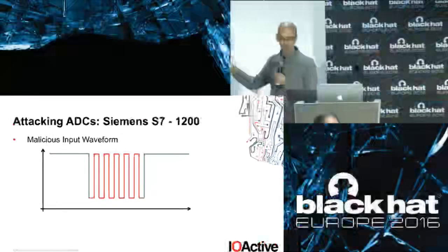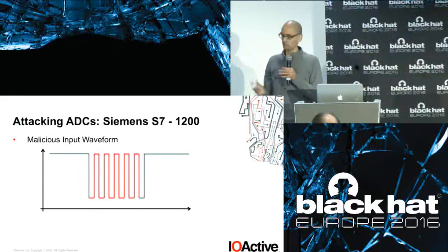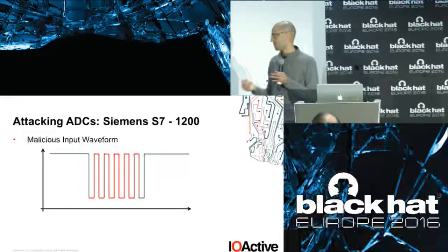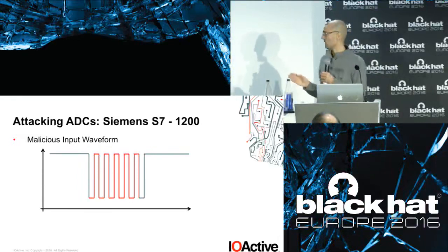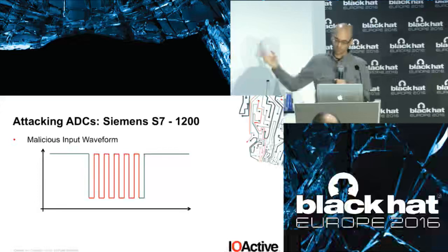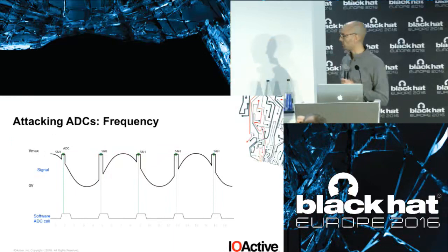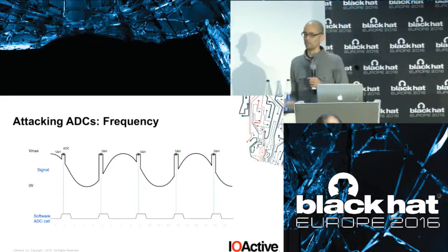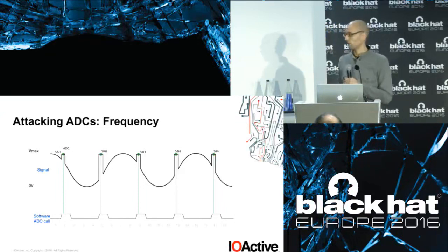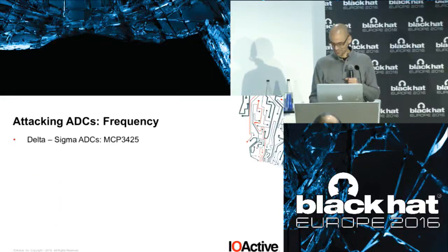So that's exactly what happened on this PLC. It's reading the signal, but it does this type of read and sleep. So during the times the PLC is sleeping, we can inject signals very fast and cause weird problems like the one that you saw. We could use that signal. This is another example of what we could use, right? On the bottom is the time that the software is actually reading, and during the other time it is doing something else. It's probably not sleeping, but doing calculations, or maybe actually sleeping. I actually did that quite a few times in the past.